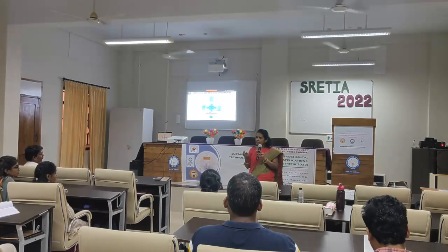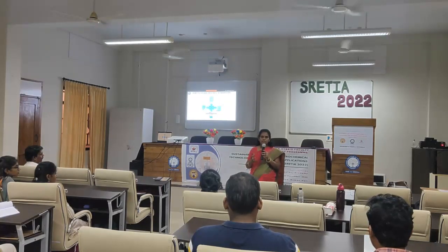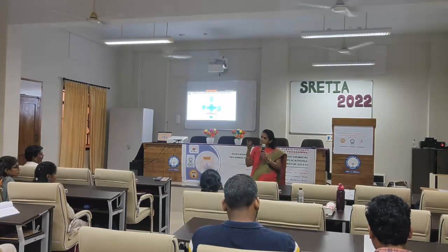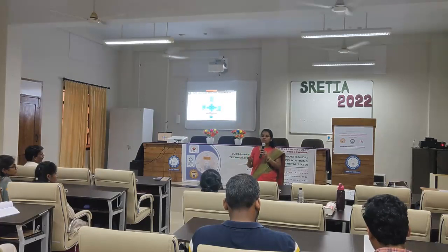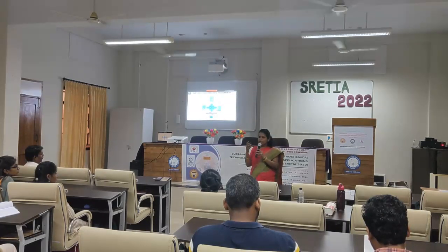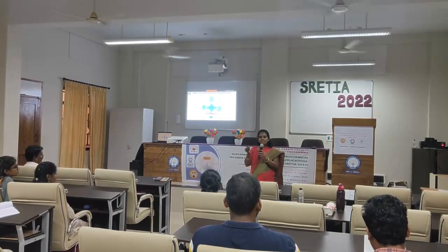What should be the factor now? The emulsion should be very stable in nature. It should be stable even for 2 months, 3 months, or at least for a week, 7 days or so, so that we can at least go through one process. For stability, emulsion stability plays a very big role. For that, we can add some emulsifiers.